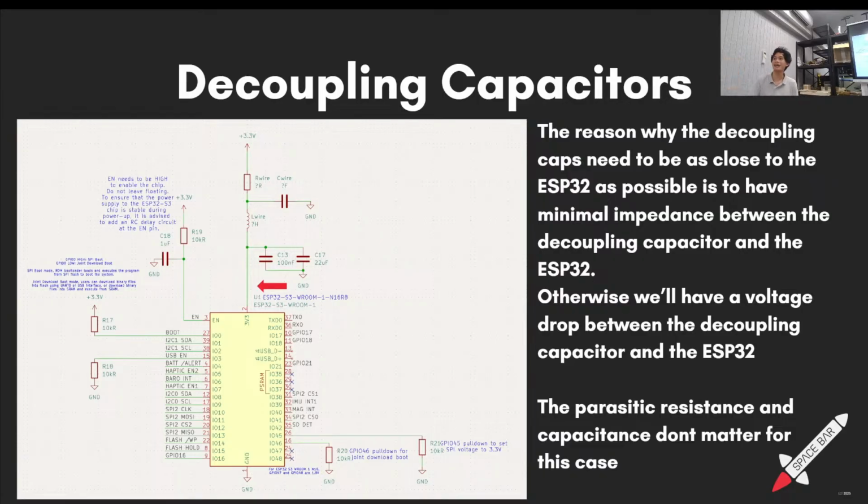Exactly, yeah. Because if you have 6 pins, right, then you've got a bunch of traces, a bunch of wires going to each pin, right? So that's got a length as well. You know, it's not 2 mm anymore. Yeah, so there's some impedance there. So the bulk capacitance is going to handle the whole chip, yes. But what about the impedances of those short lines to each power pin? That's what the tiny decoupling capacitor at each pin is handling.